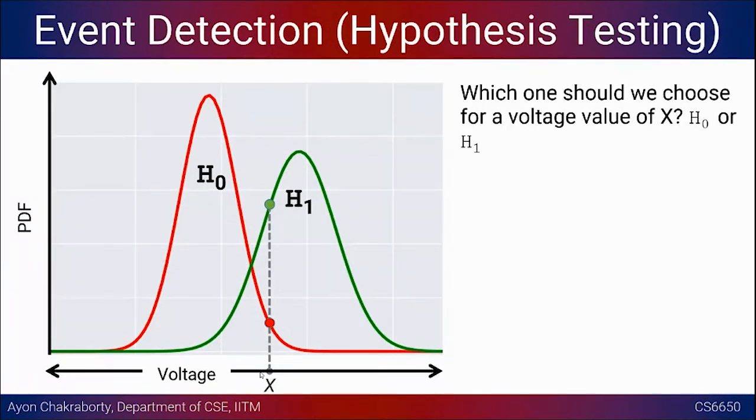After the digitization of the raw signal has taken place, I get a value X, and what I can simply do is plug in the value of X in these two distributions, n0 for H0 and n1 for H1, and I can simply plug in these two values and see which one is bigger. If you have taken a very basic course on statistics, you know these are the two likelihood values. Given the value of X, I can know in which one you are more likely to go.